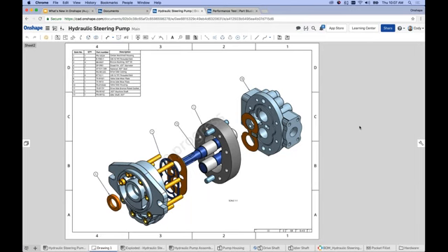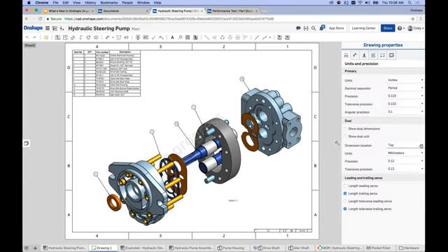And the big thing I would stress is this is now a flyout where it was once in the toolbar. So if you've been using Onshape a while, you're used to clicking the wrench icon in the toolbar. That icon has been moved to the far right of the drawing interface. So you'll see in the far right of the drawing interface a little wrench icon. This is how you access the drawing properties flyout. And again, this has changed, so just keep that in mind. Not only has it changed, but we've added a lot of new functionality that you couldn't do in the past.